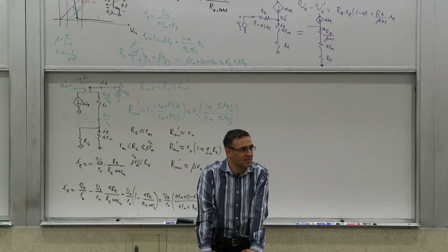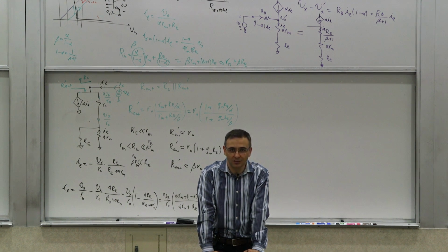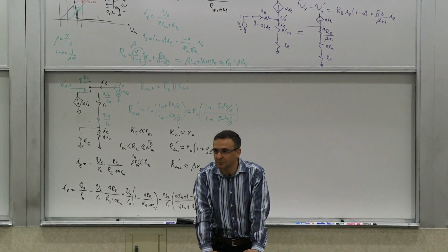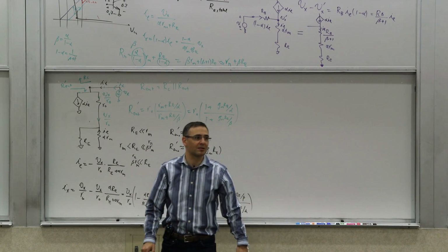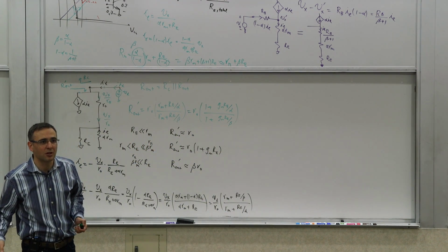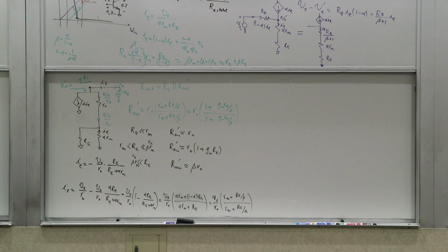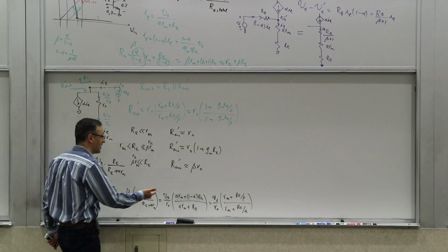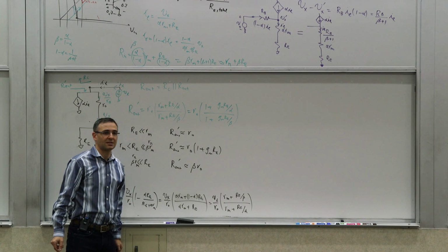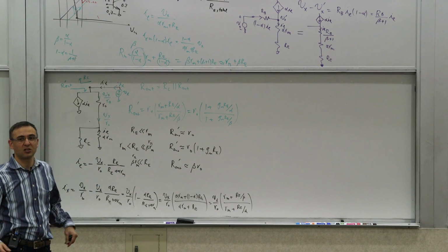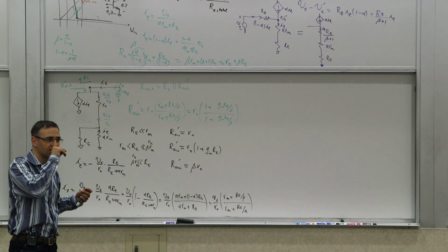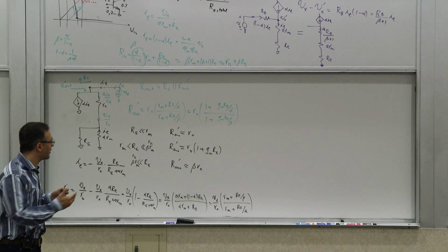If you can increase the output resistance without compromising other things, that's an easier way to do it. Because increasing the drive capability usually requires other things, like power consumption and things of that sort. So if you have a certain amount of current, you want to get, in several situations, a large output resistance. You remember we said that we are going to be on this quest for gain, right? So that's where we are going with that.